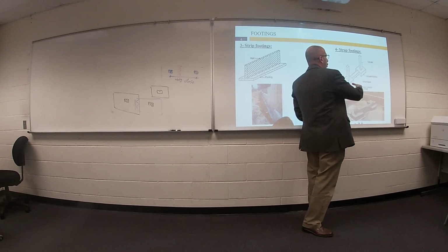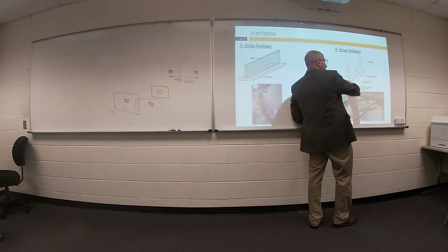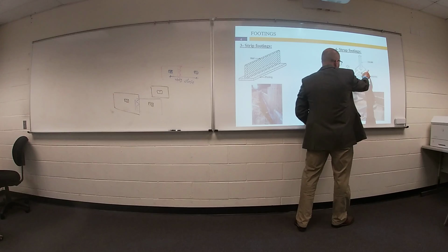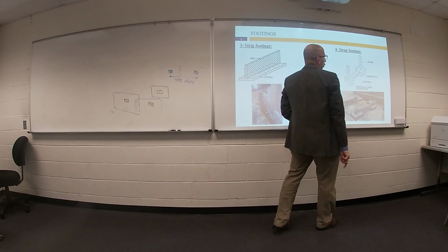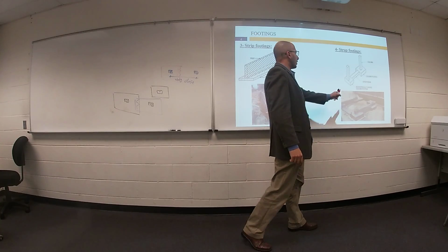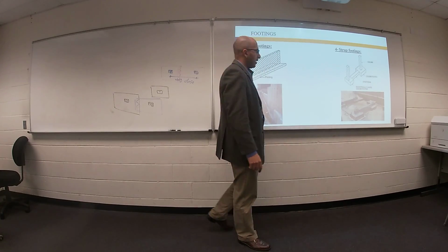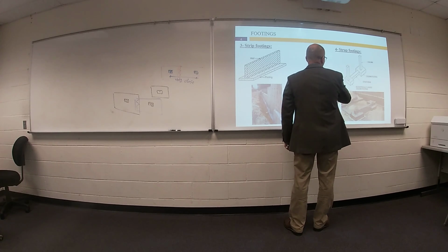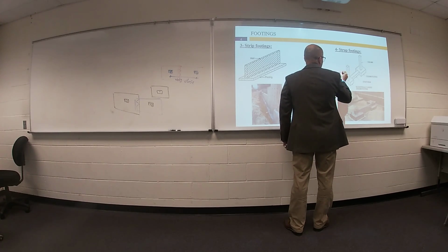So I expect overturning of my footing, so I have to connect it with the other footing with a beam called strap. At this moment, your footing is called strap footing. Most of the time, this happens beside neighbors.